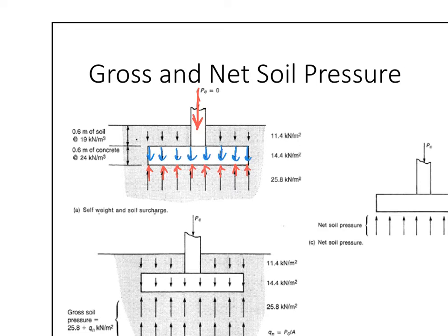And then the footing weight goes down, then there is a reaction from underneath as well, and I will also put it in blue, right? And we also know that the footing is underground, but there is some overburden. So the overburden is the green color arrows.